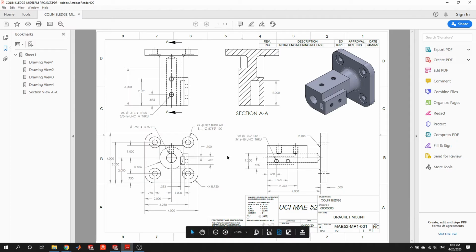So there's a couple places we could go. I think the easiest one right now is creating this little square pocket in the side rectangle. So let's take a look at this. We see that it is a width of 0.313 inches. And actually, when you're looking at a drawing in inches specifically, because this has been rounded to 3 decimal places, then we see 0.313, which may look a little bit strange, but actually this is 0.3125, which is a common fraction of an inch. So if you want to put in those 4 decimal places, we're only going to show 3 on the drawing, and 3 is still correct here.